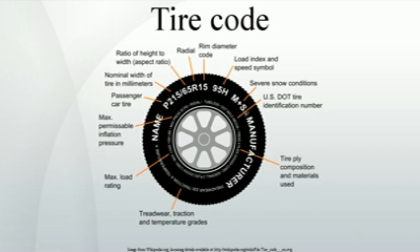An example, a P205/50 R15 standard load tire has a load index of 84 and a load rating of 505 kg, 1,113 pounds, at 35 psi, 240 kilopascals. A P215/50 R13 with the same load index of 84 only has a load rating of 495 kg, 1,091 pounds, also at 35 psi, 240 kilopascals.